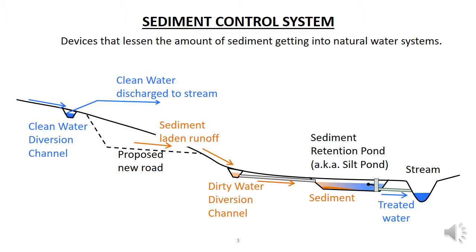First, we want to minimize the amount of runoff that we have to treat. Less water to treat means the treatment devices can be smaller and cost less. We can minimize the area of earthwork we open up and re-topsoil the plant surfaces once we have completed the earthworks in that area. We can also intercept rainwater before it flows onto the site.